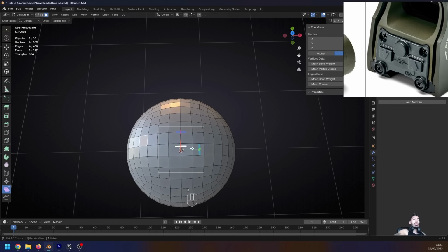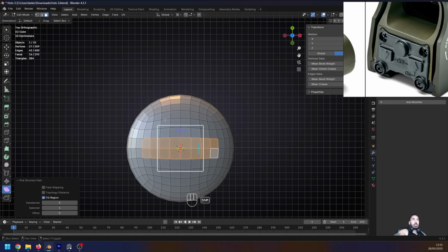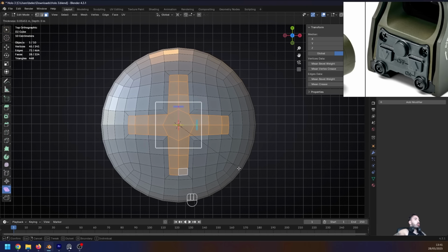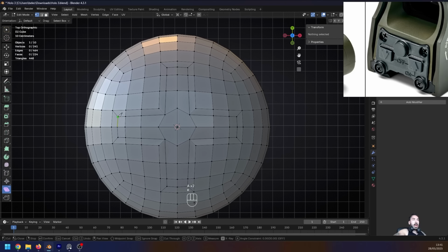And then we just have to use this geometry on the top to create a little plus shape. So let's go to top view. We're going to select a plus shaped surface like this on both axes. And then just inset this with I so the geometry works a little bit better. Now we just have to straighten out these edges. And to do that, I'm going to use my knife tool. So I'll click over here and then I'll bring that over to the other side.